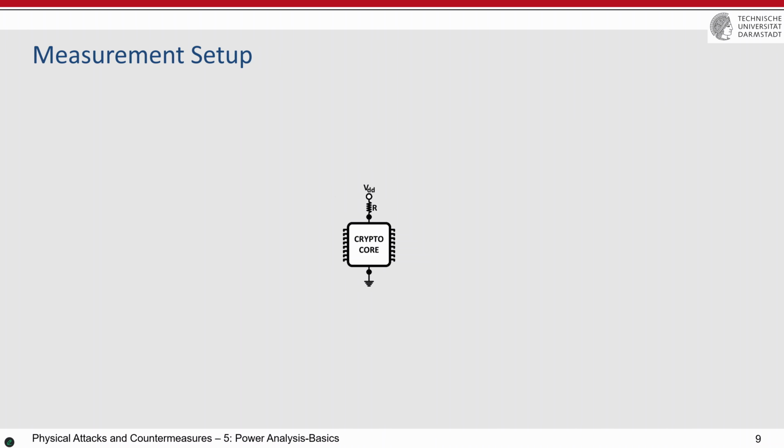But then the I/O voltage is different. I/O voltage means the voltage level at which this chip is communicating with another chip. There are different technologies. Super old technology is 5 volt, means that the communication between chips was such that zero value was close to 0 volt and logical value 1 was close to 5 volt. It became 3.3 volt afterwards, and then 2.5 volt, and then afterwards 1.8 volt. Yeah, they are, let's say, standards. And below that, we don't go for the I/O because it has a high effect on the noise, and then it might be noisy, and the devices cannot communicate with each other easily.